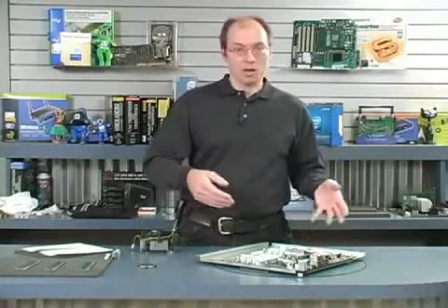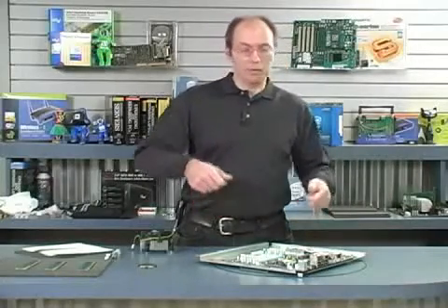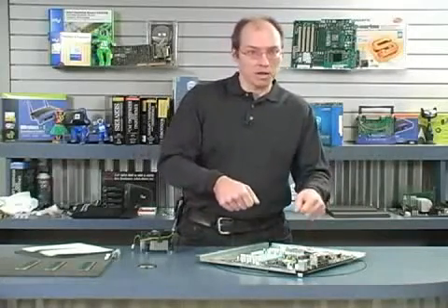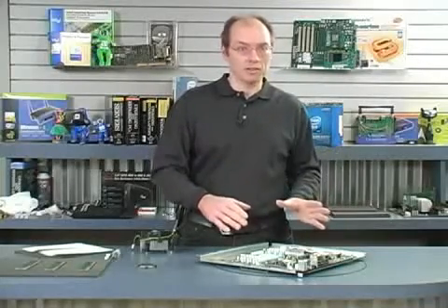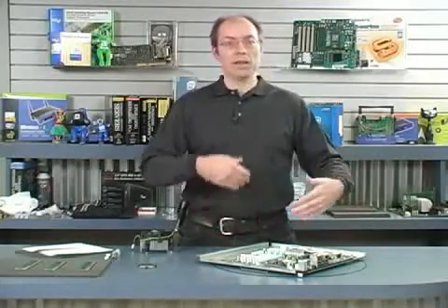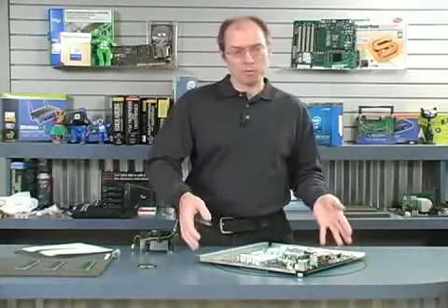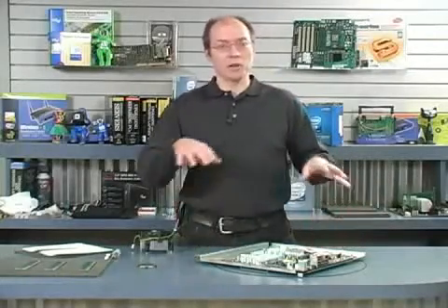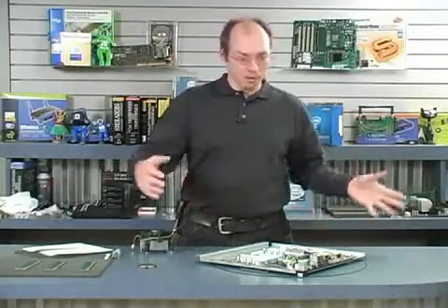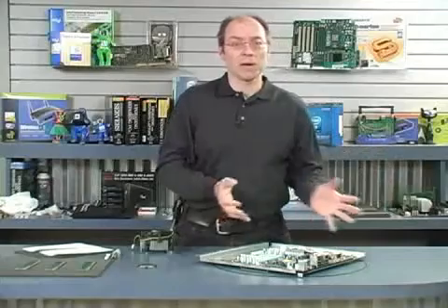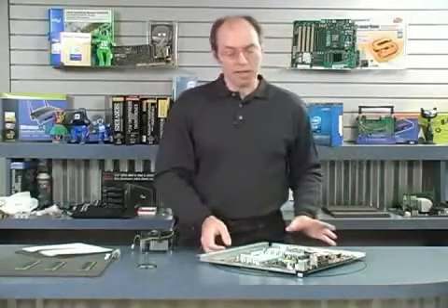You can't really install the processor and the heatsink with the motherboard out of the system because you have to put a lot of pressure, particularly when you install the heatsink, and it's normally best if the motherboard is already installed. Well, that's where, in the other segments, I've talked about having a chassis that uses a removable motherboard tray, because that means you can install the processor and heatsink and memory with the motherboard essentially out of the system, without the confines of the case around you, making it difficult to see what you're doing and get your hands in there and everything like that.